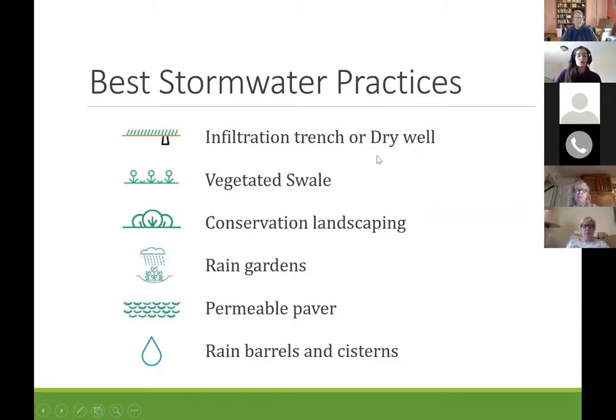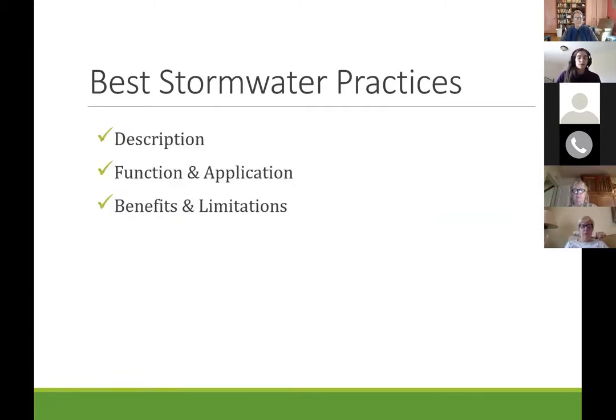Generally, with homeowners, we talk about dry wells as a smaller scale for a single home on a lot. An infiltration trench is sort of a scaled up version of that practice. So it's just a larger size facility meant to take more stormwater, more downspouts, more runoff. It's just larger than those dry well systems. So we're going to breeze through a couple of these to try and describe some of them. Some of them I've left off.